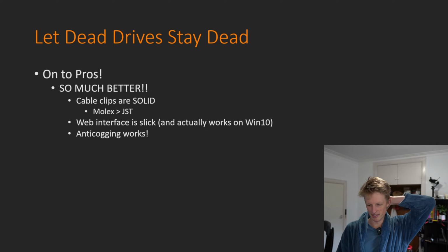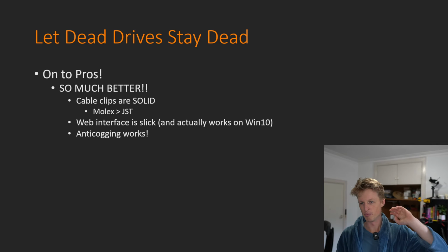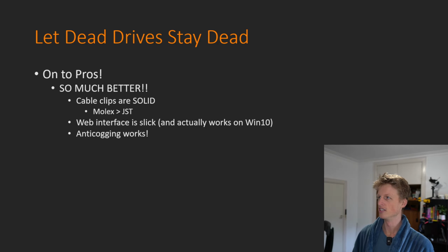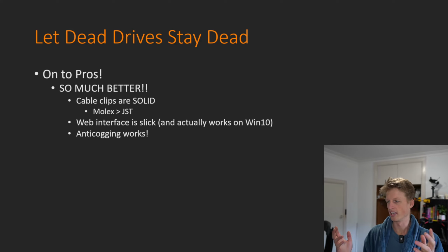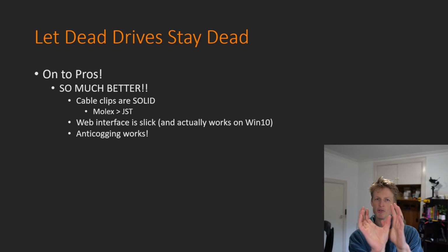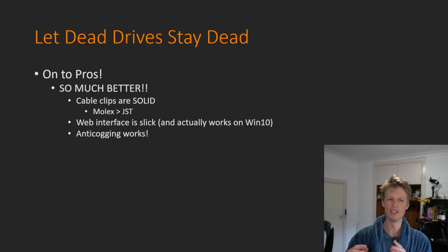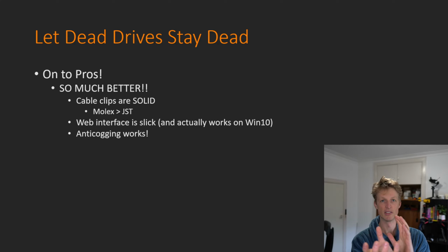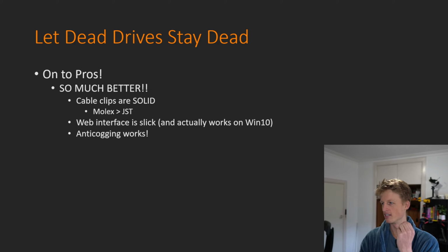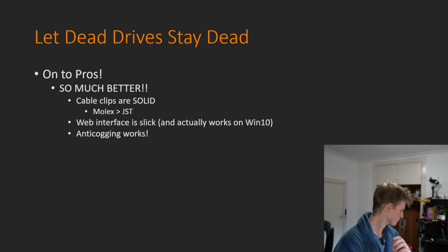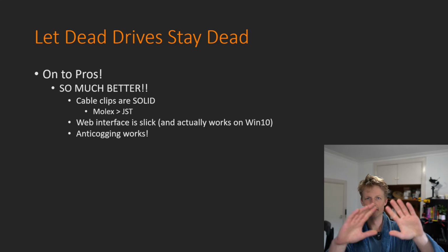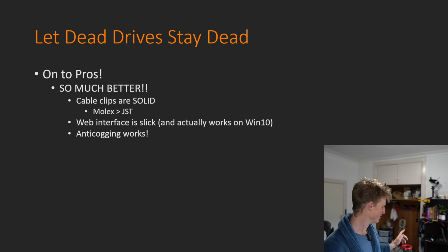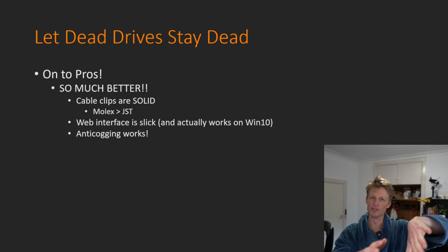So I'm very conflicted about this because it means it's going to be a lot of work, but anti-cogging basically allows you to control the motors really, really slowly. If you try to do this without anti-cogging on, then the motor tends to just jump. It will move a little bit and then just skip, and the motion will be really erratic. But with anti-cogging on, they can control the motor really smoothly at still a very slow speed, which I'm really excited about, because it means that I'll be able to use Jugglebot in the Stuff Made Here style edutainment video. I'll be able to move Jugglebot really slowly, and I think that will look very, very cool.